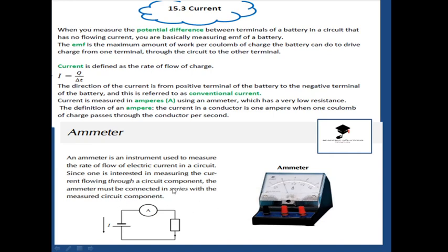We will come and look at what is called a series connection and then a parallel connection. But what it simply means is that it must be measured within the same path. This is what the ammeter measures here. So when you put the ammeter here while the current is flowing through a load, which is a resistor, then we can measure the current through it.